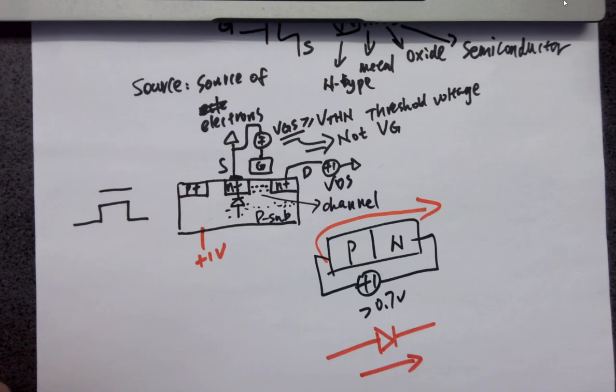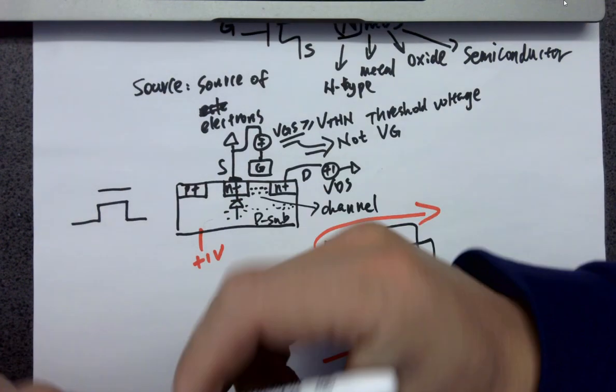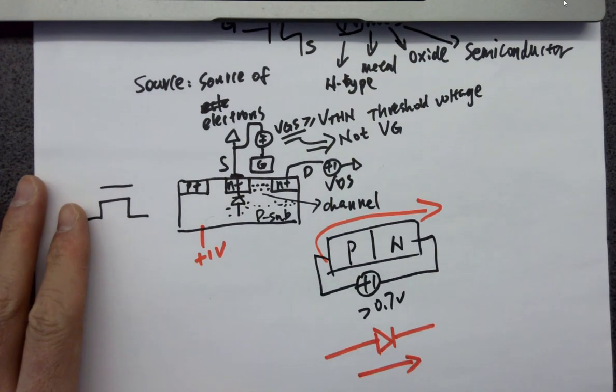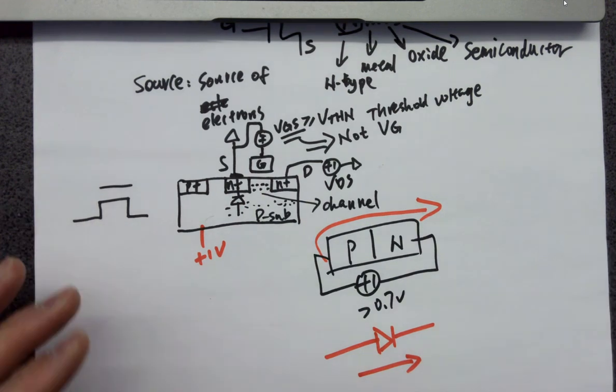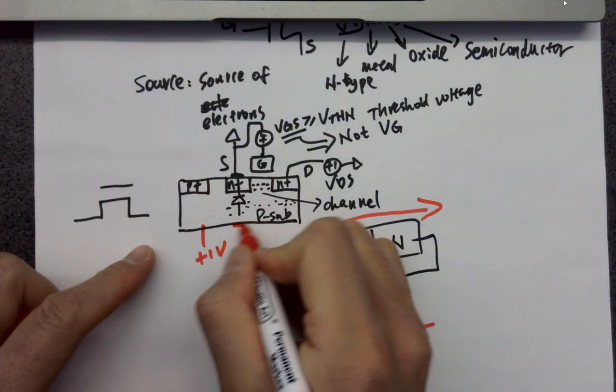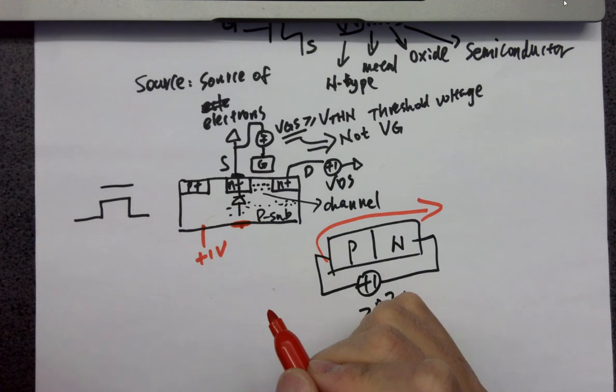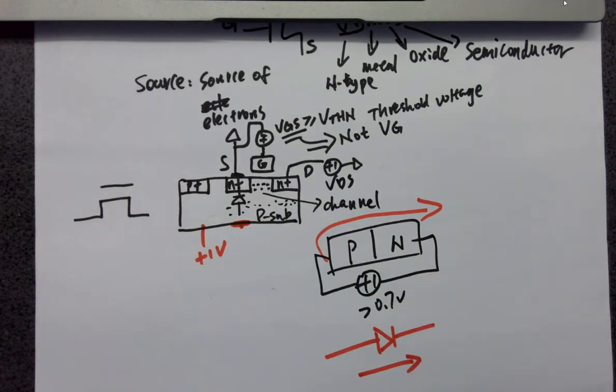So what we want to do? Do we like it? No. Higher threshold voltage means you need a higher voltage to turn it on. Okay, especially for this low voltage technology or very small technologies, you need like just 1 volt to turn it on. So the threshold voltages are around like 0.3 volts. So how to do it? Ground substrate how? At the back of the wafer? No, there's no way to do that, right? Like you welding a wire on the back of the wafer at the bottom and looking at the bottom of the wafer? No.